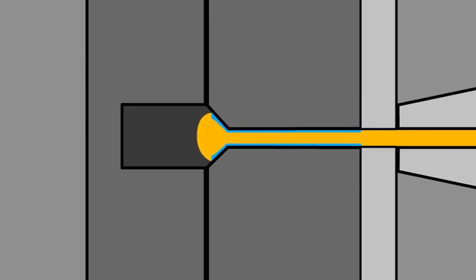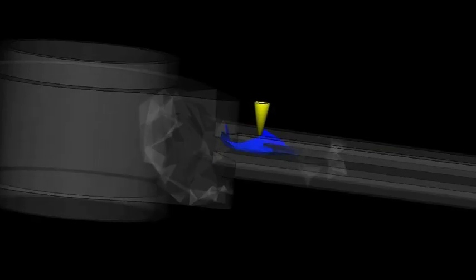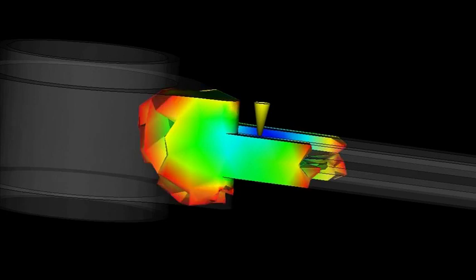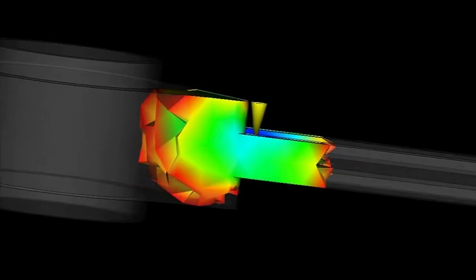Temperature, pressure, and volume vary through the thickness of the part, so the flow of molten plastic through the part changes. It's vital, therefore, to model the thickness of the part properly to take into account these variations in temperature, pressure, and volume. In order to account for all the dynamic properties of molten plastic, Autodesk Moldflow analyses rely on a finite element mesh model for accurate results.